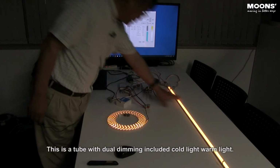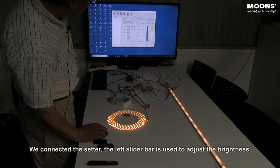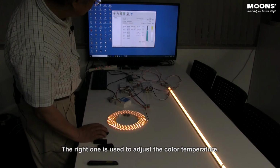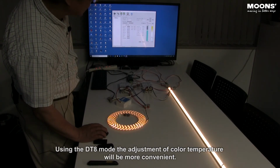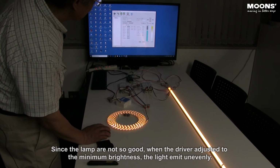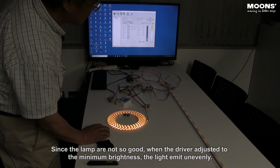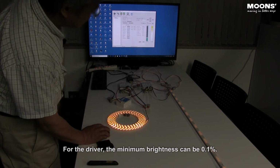This is a tube with dual dimming included: cold light, warm light. We connected the setter. The left slider bar is used to adjust the brightness, the right one is used to adjust the color temperature. Using the DT8 mode, the adjustment of color temperature will be more convenient. Since the lamp is not so good, when the driver is adjusted to the minimum brightness, the light emits unevenly. For the driver, the minimum brightness can be 0.1%.